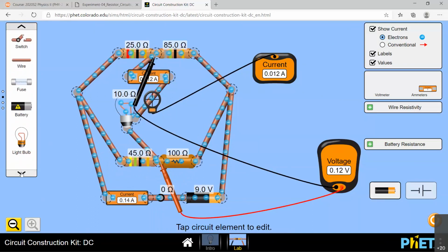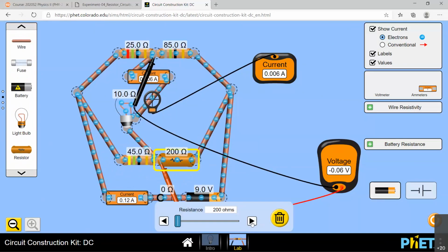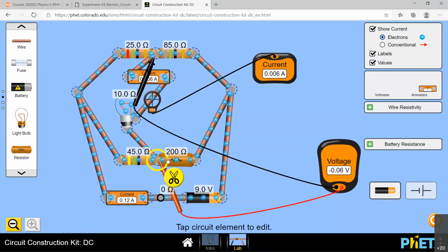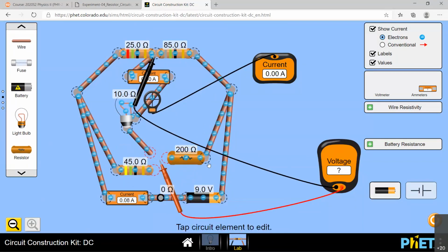You have to bring that new resistor here and then replace the R4 with it. Now you can go above 100. Now change it slowly. The only problem is that you can't go to small numbers. That will be a problem. The best way is adding two resistances together.